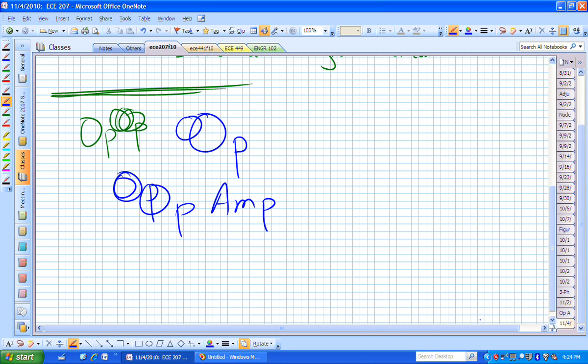What I would like for you to be able to see is the right side of that R sub 1. The SPC is the summing point constraint. I wasn't very clear on that, maybe. But now if you look at this, the right side of the resistor R sub 1 is effectively tied to ground, isn't it?